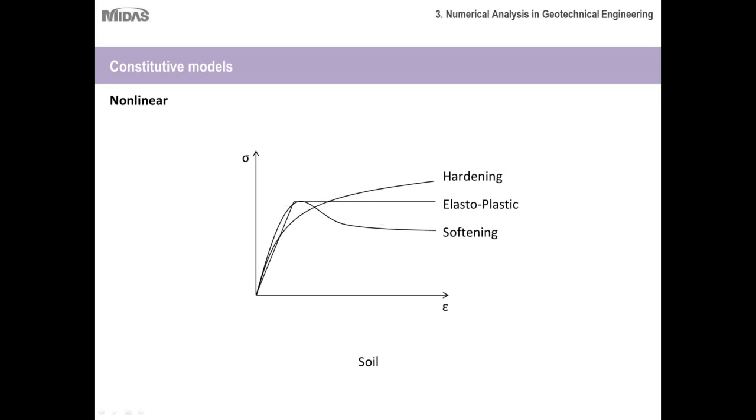That's why numerical modeling is so key: it can take the various equations that are related to each of these soil behaviors. For example, for each line you need a different set of equations. You need to break it up. But with numerical modeling, all those equations can be inputted, and you'd be able to account for nonlinear behavior in a much more efficient way than doing it through a spreadsheet or by hand.